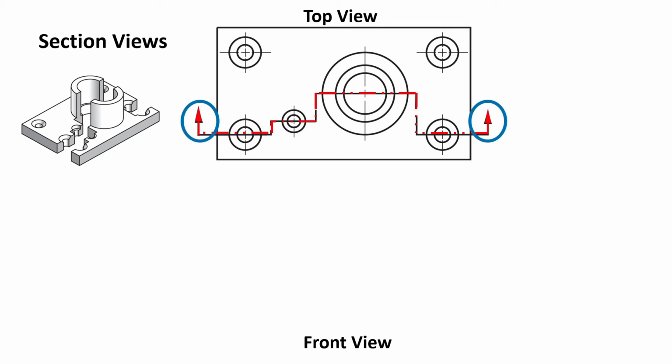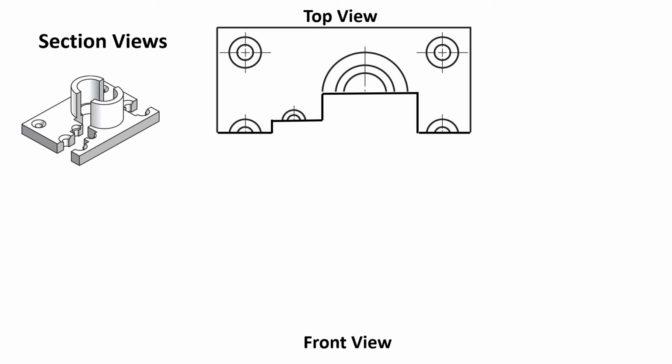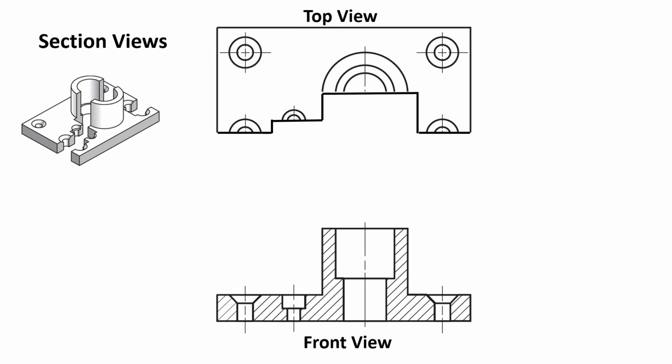Think of it like this. Anything on the back side of the arrowheads is cut away and disposed of. Now you look at the cut surface of the piece you have left. This surface is seen in the front view. The arrowheads of the cutting plane line point your eyes in the direction telling you to look at this surface. This is now what you will see.